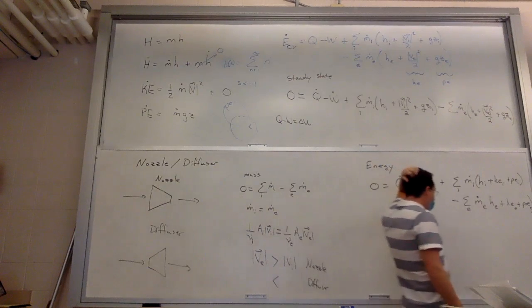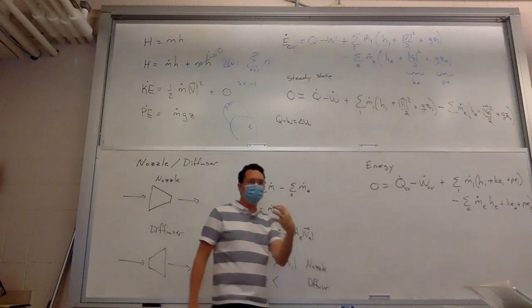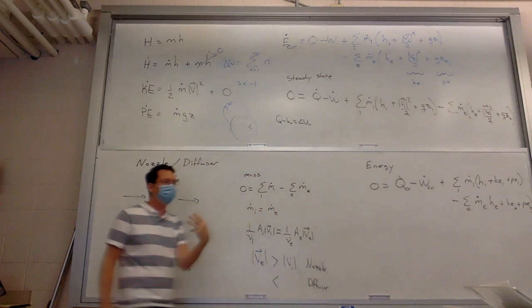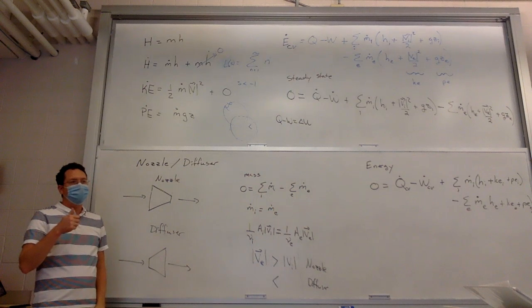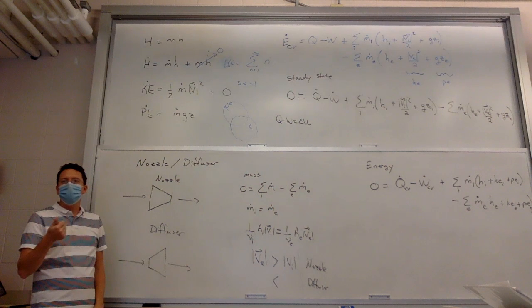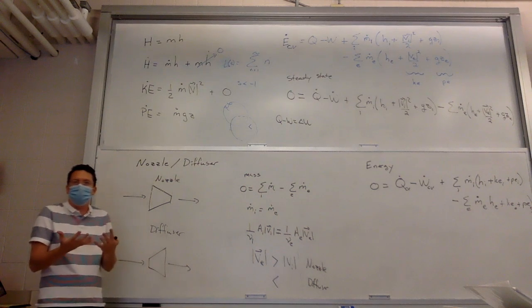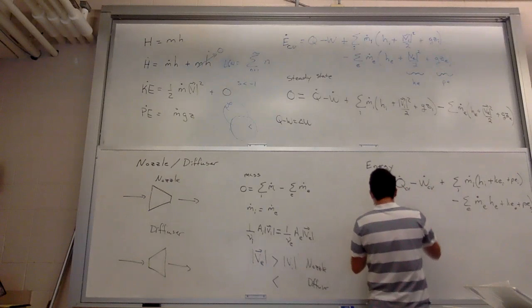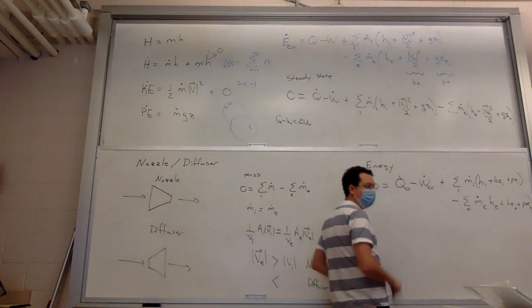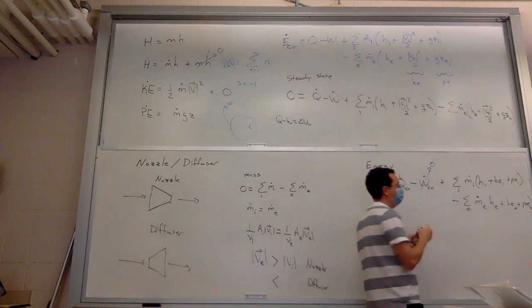Now, a nozzle is a passive device. Right? That's why they're so cheap. You just taper something. So there's no turbine spinning, or there's no work being done. There's no electrical work going in. It's a dumb device, right? So what are the assumptions we can make? No work. Yeah. The work is 0.